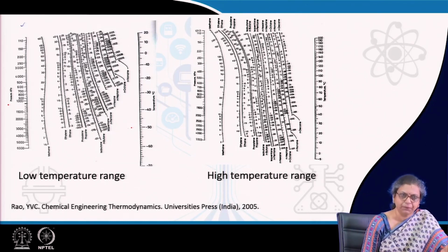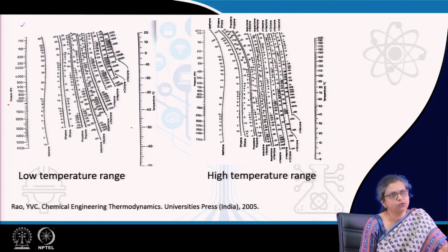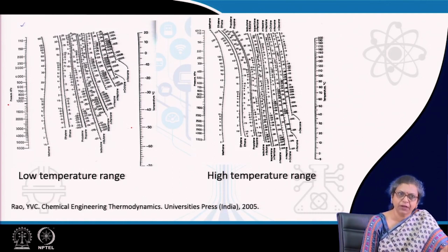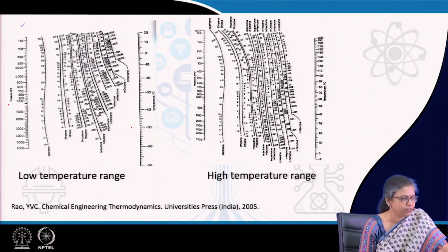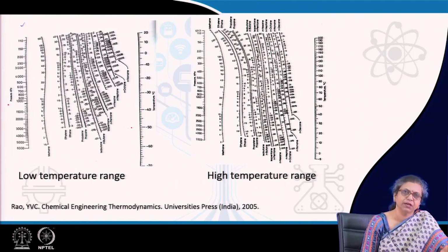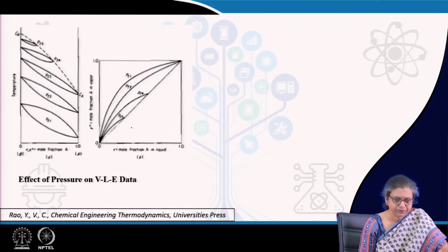For other substances, as we go into distillation, you will find that quite often we give you the data on alpha, right. And there can also be some situations where the equilibrium data, either in terms of Txy or in terms of xy, are available. When that is there, then you can use that as well.